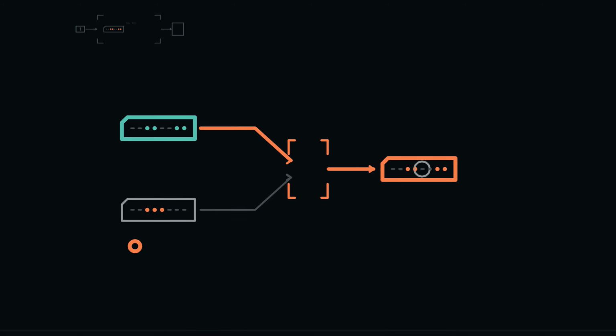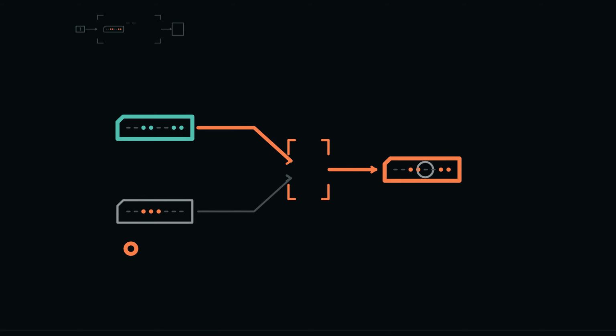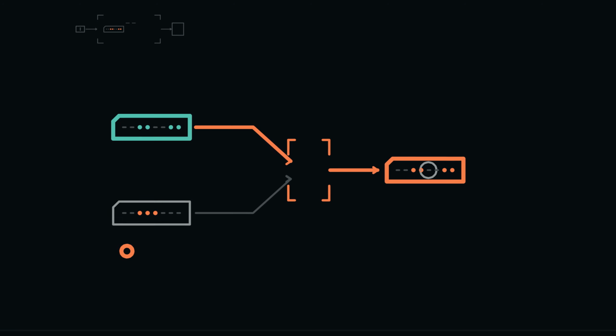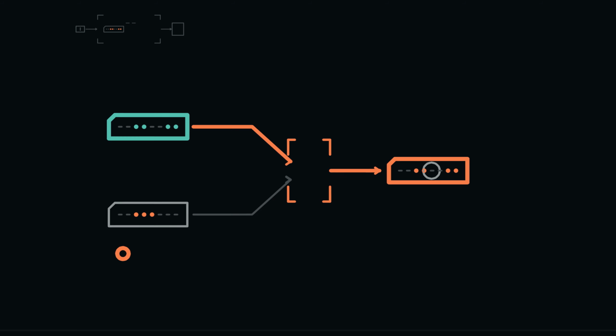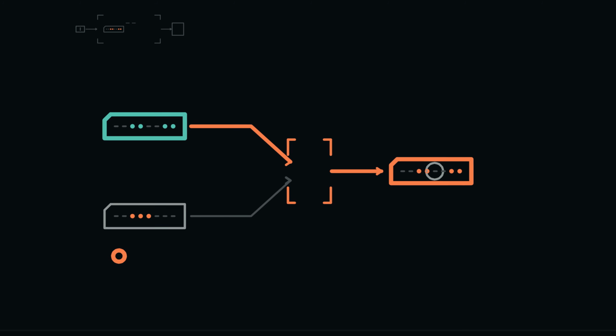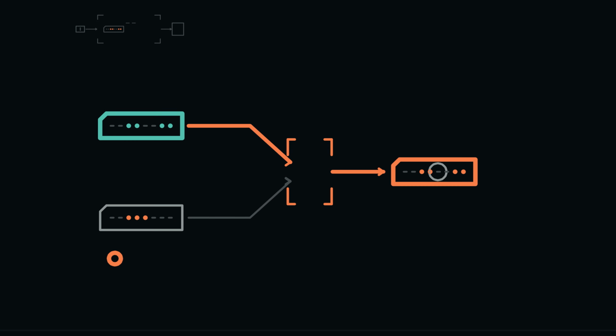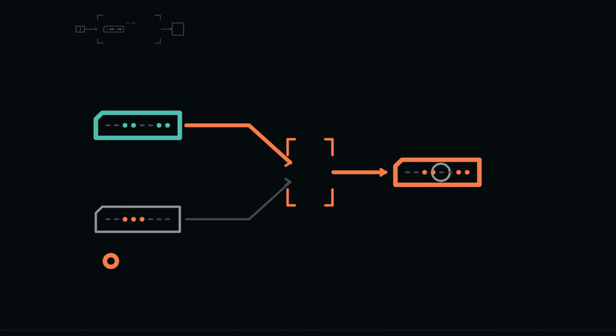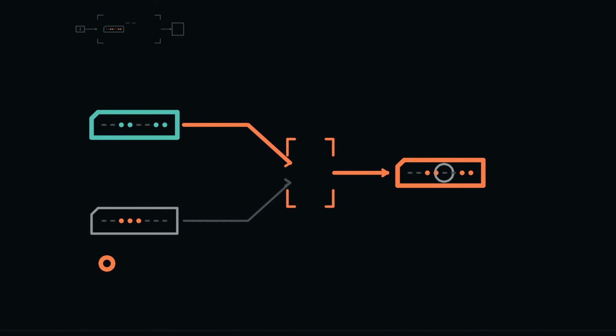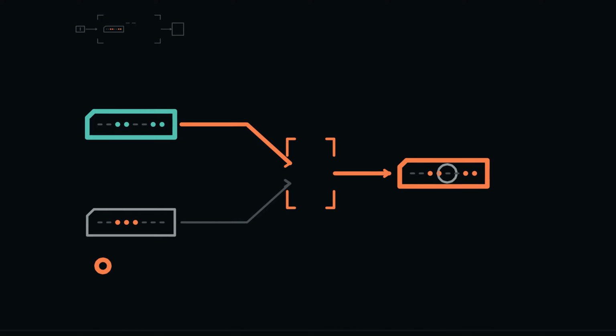Set A to 1 and B to 0. Before select moves, predict both possible outcomes. At select 0, the A path is enabled and the output is 1. At select 1, the B path is enabled and the output is 0. Now exchange the candidate values while leaving select at 1. The output becomes 1 because it follows B.